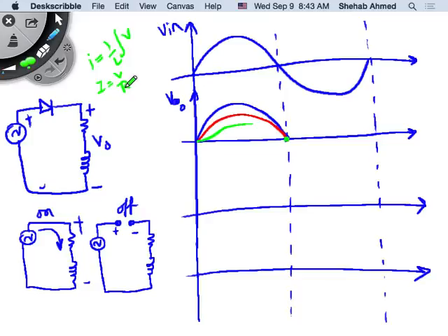How about in an inductor case? We said that the current will always be delayed, right? So if the voltage across this RL circuit went down to 0, is the current going to fall down to 0? It will not. Because of the inductance effect, there is a delay in the current falling down to 0 versus the resistor case. They always draw the resistor case first and then see what happens next.